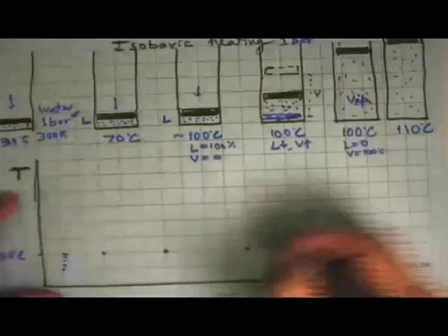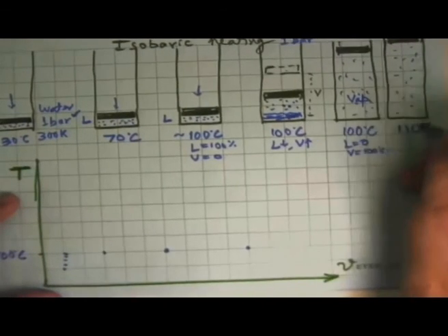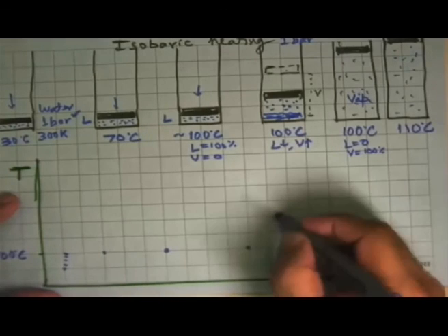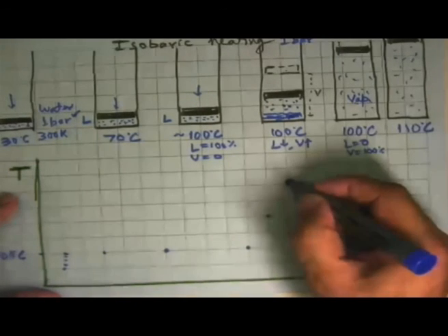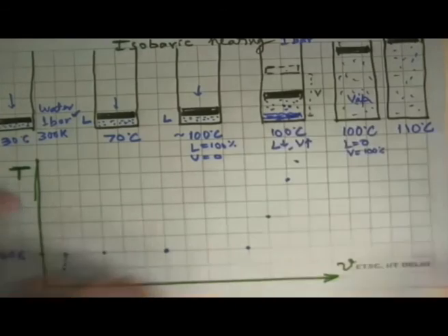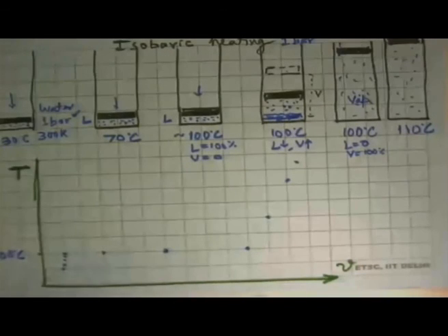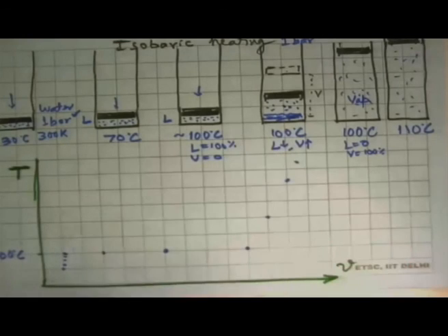So this point would then show that temperature has increased, volume has also increased, so it will go this way, and we can get a point there. And if you continue heating, these points will keep going like this. Some example I have taken of water, but one can do the same thing with practically any substance. You can say take nitrogen at 77 Kelvin, or say nitrogen at 1 bar pressure starting from 70 Kelvin, it will do the same thing. Take butane, take a particular pressure and start from say 10 degrees Celsius and start heating it, it will do the same thing. So all substances under certain pressure and temperature conditions will have this behavior.